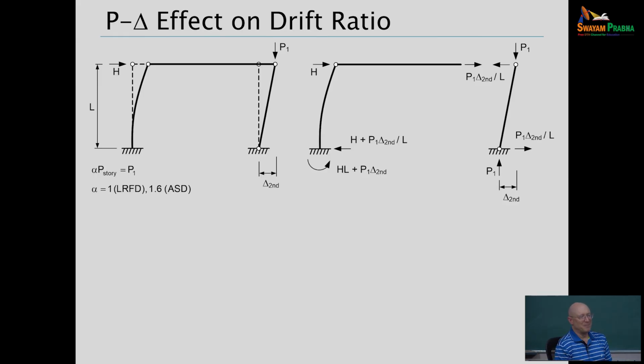Well, in ASCE 7, we have a 1.4 times dead load. Divide that by 1.5, and you've got a load factor less than 1. So some engineers look at that and worry. Oh, and you've got a resistance factor on the other side. It's okay. And then 1.2 dead plus 1.6 live, divide that. Okay, so the engineers that prefer ASD want to see dead plus live. That's our load combination, dead plus live.